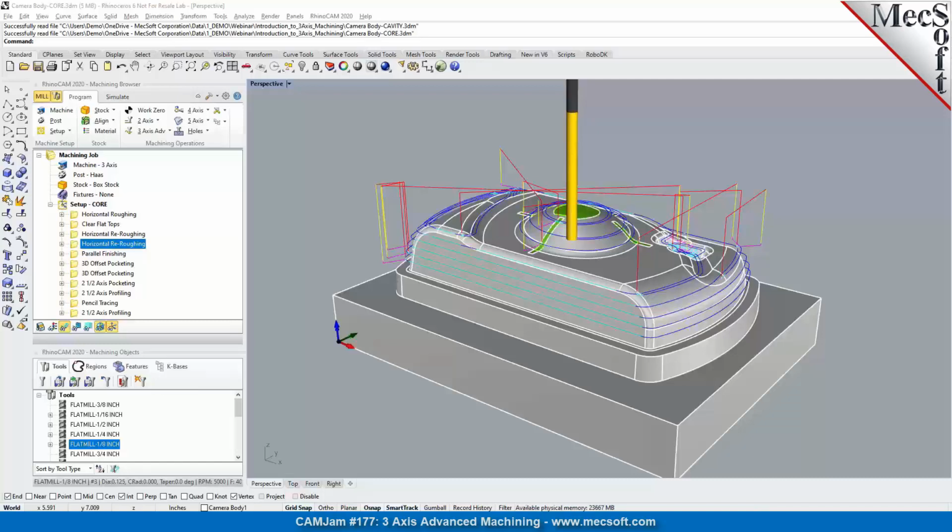contacting the fillet. And so in those kinds of situations, you're going to run into jagged toolpaths, because the machining algorithm is thinking, oh, the cutter is touching in multiple places, and then it moves to a different location, and it's not touching in so many places, or maybe not touching at all, as in the case of a very variable radius fillet. So those are things you need to keep in mind when you're using these pencil tracing and valley remachining methods.